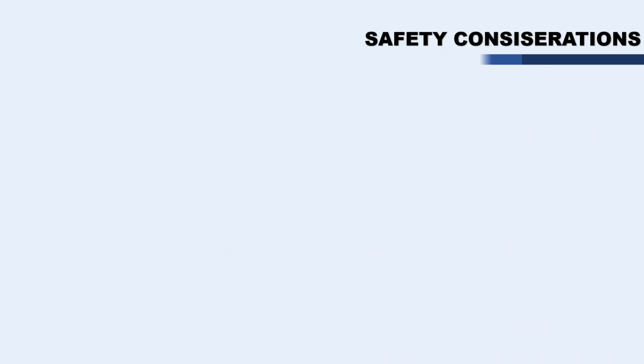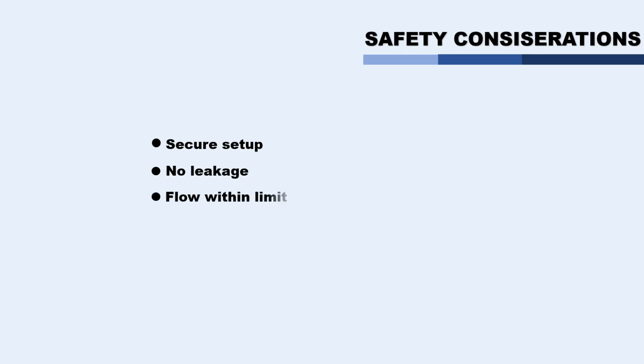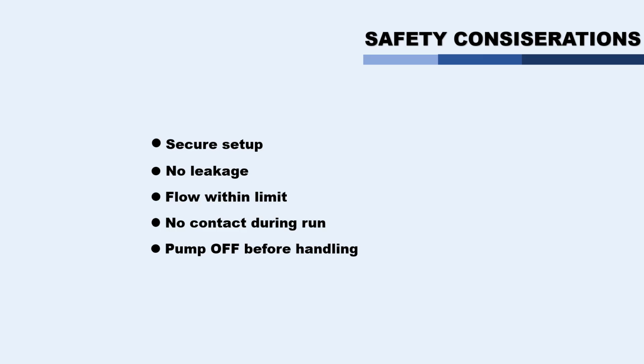Regarding safety, secure mounting and leak-free connections must be ensured. The module should be operated within the specified flow range to prevent carryover. Hands must be kept away from the module during operation, and the pump must be switched off before any adjustments. Proper lab attire must also be worn at all times.